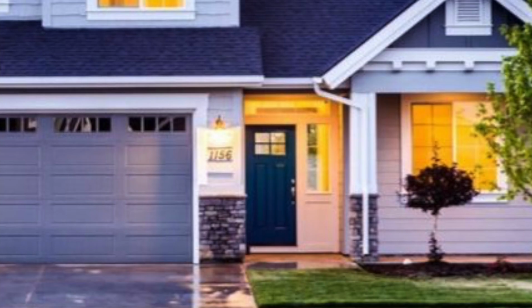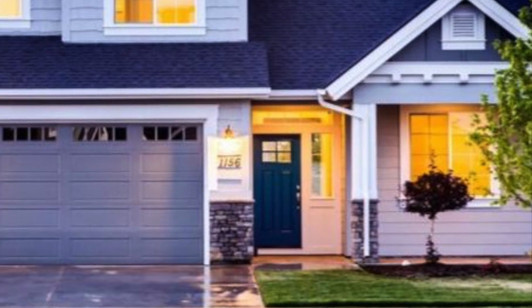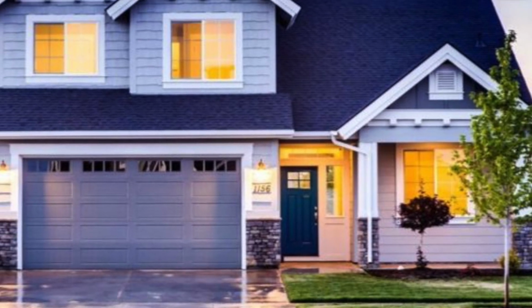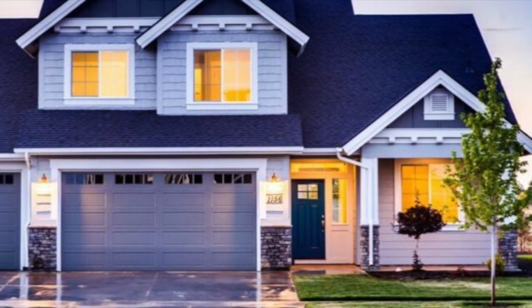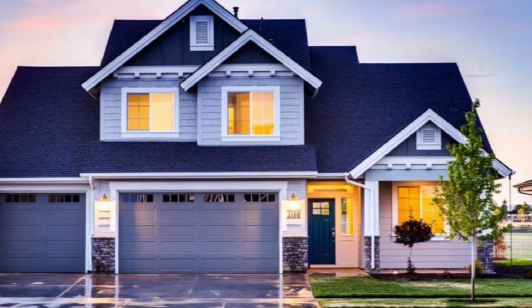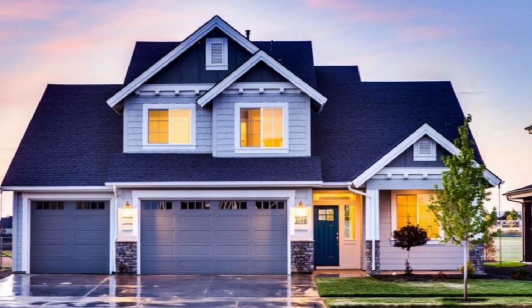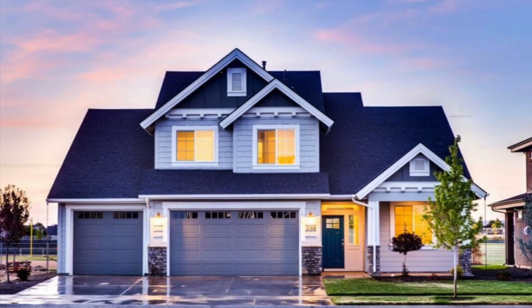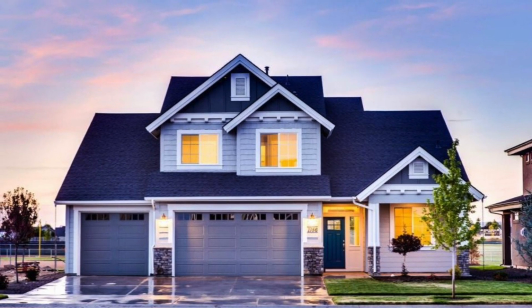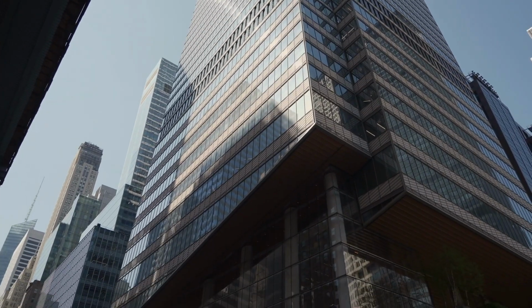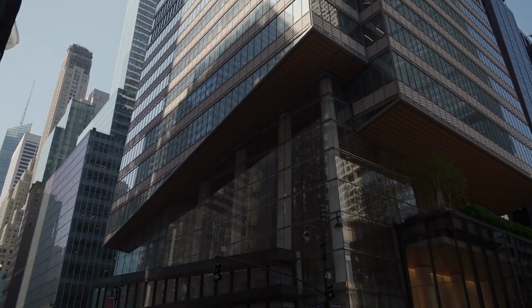For example, if you walk out your front door and then turn around, you'll be looking at the front of your house, like this photo shown on the screen. From this viewpoint, you're seeing the house in elevation view. The same would be said if you're looking at it from the back or from the sides. But the important thing to keep in mind is that the elevation view shows a perfectly perpendicular viewpoint in the vast majority of cases. But that being said, it can also be useful to have a viewpoint from an angle rather than looking straight on. This is what's known as an axonometric view.